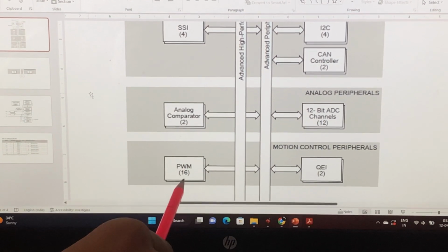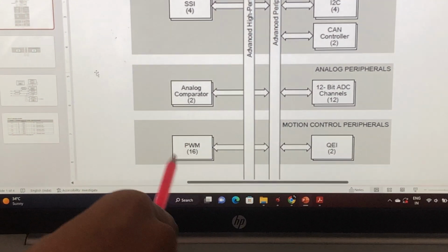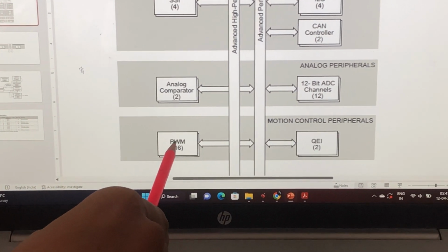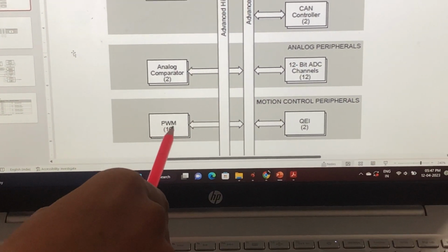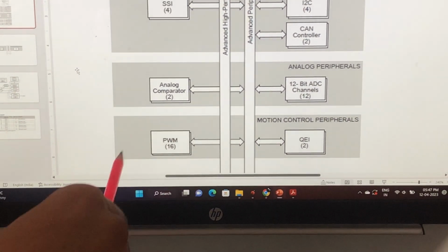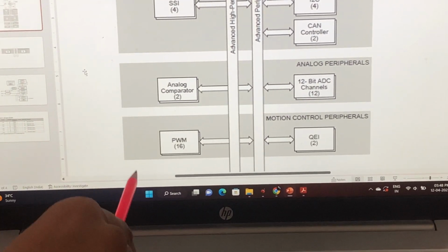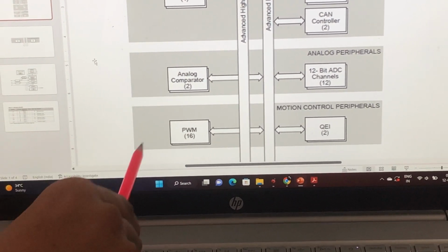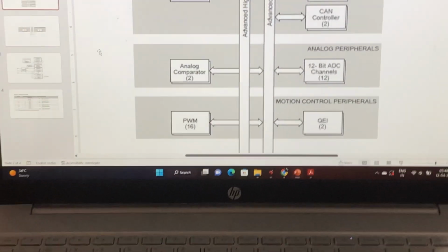If you take a motor, let us say a DC motor, rotating at 1000 RPM, how do we know the DC motor is rotating at 1000 RPM? The PWM gives the voltage and the corresponding current requirement to the motor, and the motor rotates at some RPM. Whether the motor rotates at 1000 RPM has to be identified. To identify that, something like this rotary encoder is needed.